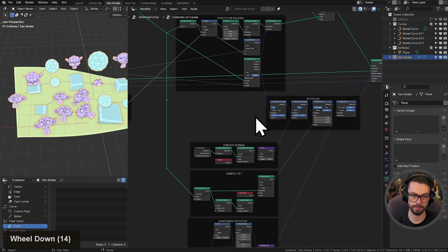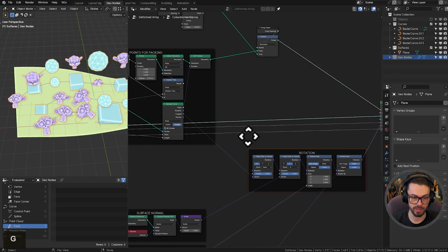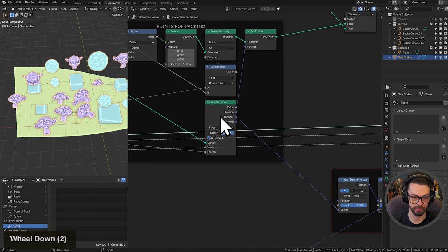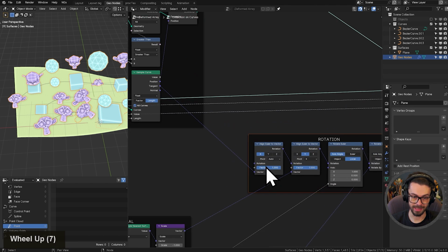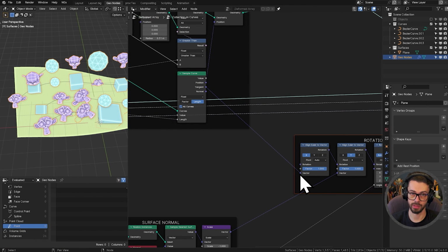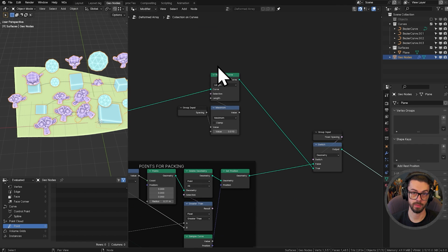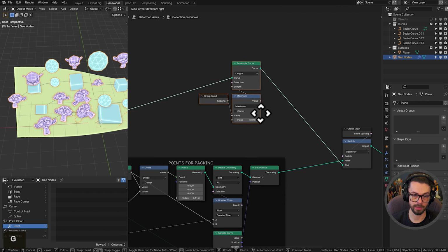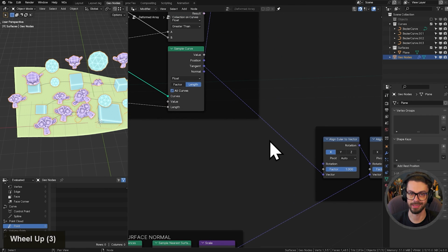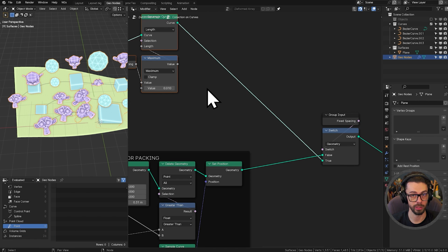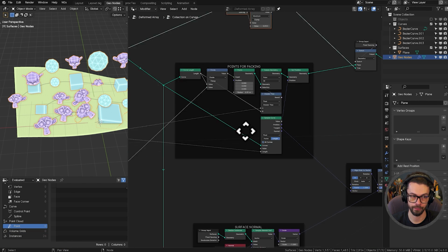And the problem is actually that when we are using our rotation, the first thing that we do is we use the sample curve based on the length from our instance packer. So this is actually not the tangent at the position of these points. That's a problem. We need to make sure that when we have fixed spacing turned on, we're also going to be using the tangent from their own curve rather than trying to sample the position based on some other calculation.